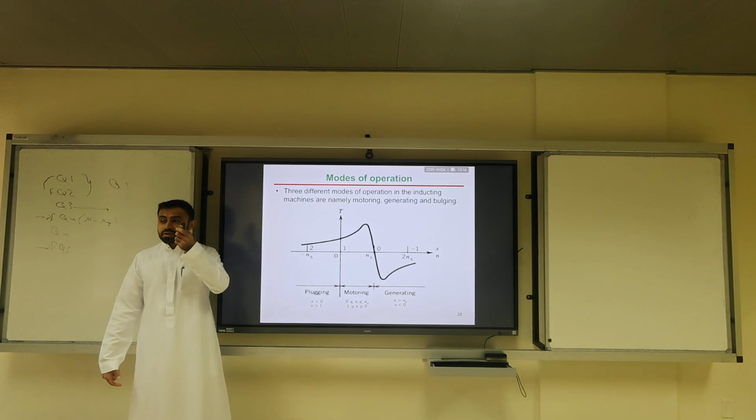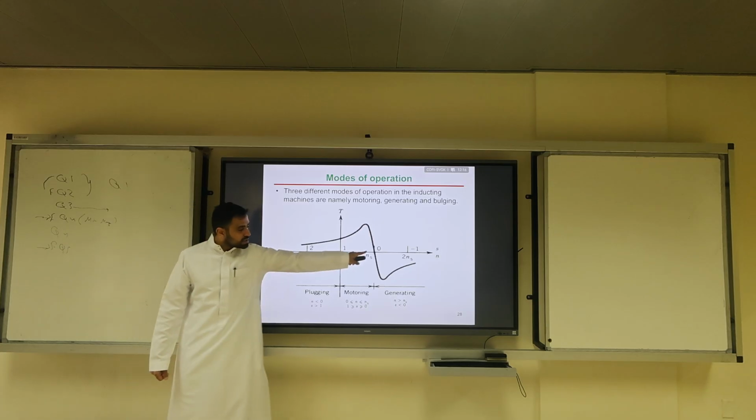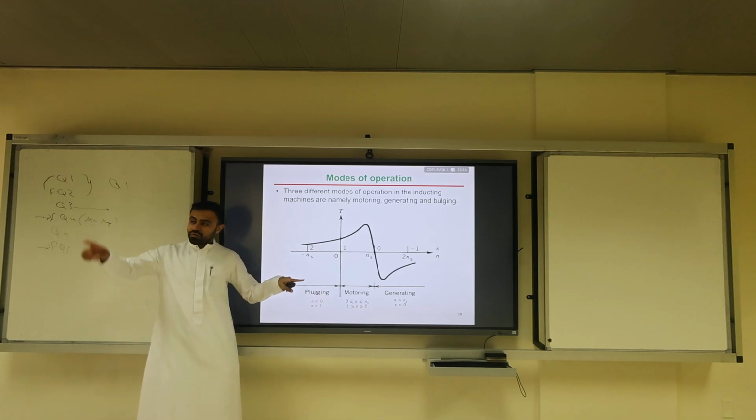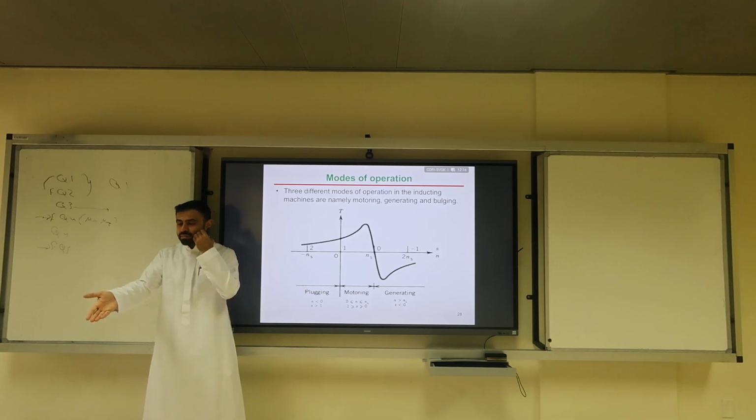So electric vehicles use a very smart technique. What do you notice about the speed from 0 to minus ns? It is the same as this speed, but it's negative. So if the rotor is rotating counterclockwise, it has to be rotated clockwise, and vice versa. But can this be mechanically feasible? Can you hit a command while the car is driving 100 miles per hour and tell it, shift your direction of rotation? That's not a good idea.